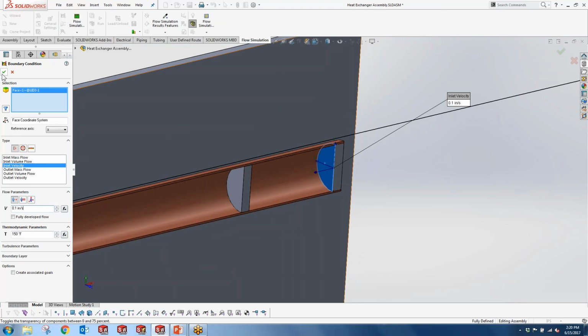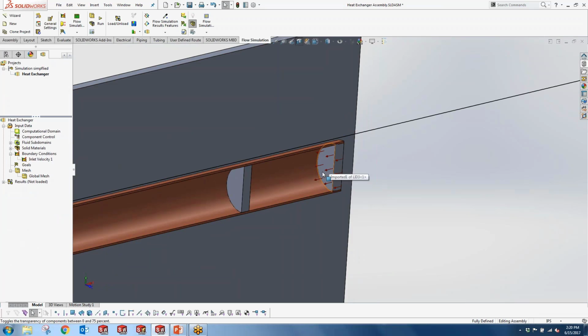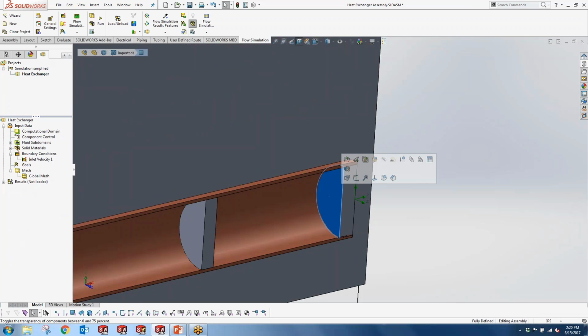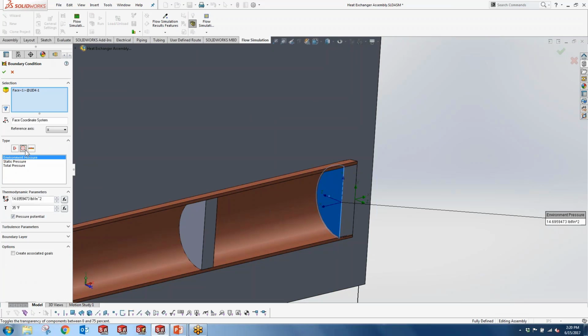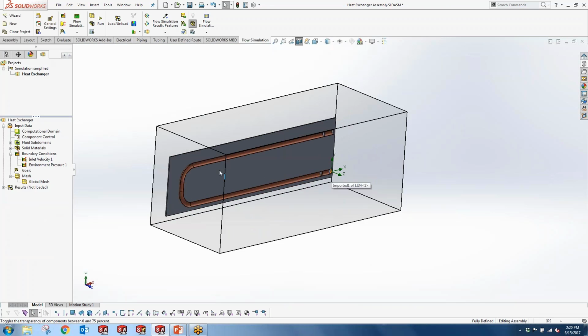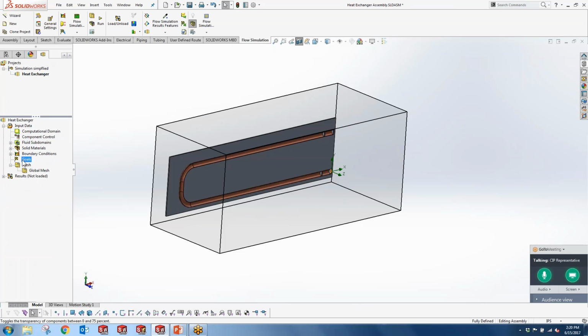So now we've got the flow coming out the way that we want it to out of that opening, but it's going to flow, run around, and then now we need to set this surface to let the fluid exit. So in this case, the easiest way to set up an exit like that is to select the pressure opening setup and grab just an environmental pressure, and that'll let the solver decide what conditions it needs to put for the flow to kind of balance out at that boundary. So there we now have an inlet and an outlet. So those are our two boundary conditions.